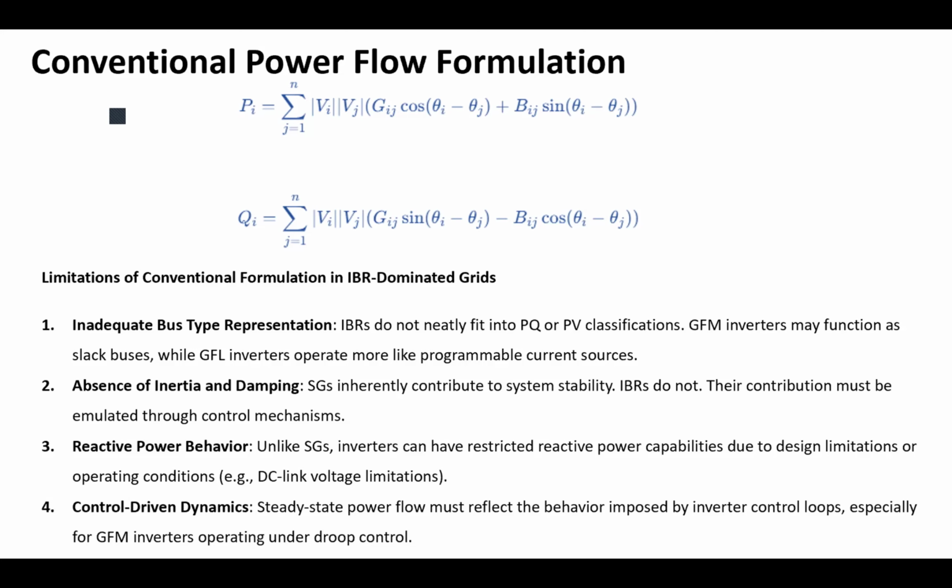Based on that, we describe our buses as PQ buses when the active and reactive power of the bus is known, PV buses when the active power and the level of the voltage, the amplitude of the voltage, are the known variables, and slack buses when the voltage and theta, the phase angle of that node, are known. So we have those three references.